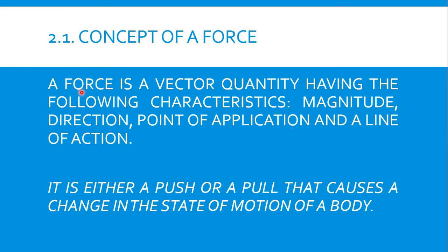Concept of a force. A force is a vector quantity having the following characteristics: magnitude, which is the size of the force; the direction, which is where the force is going; the point of application, the exact location at which a force is applied to a body; the line of action, which is the geometric representation of how the force is applied. It is either a push or a pull that causes a change in the state of motion of a rigid body.